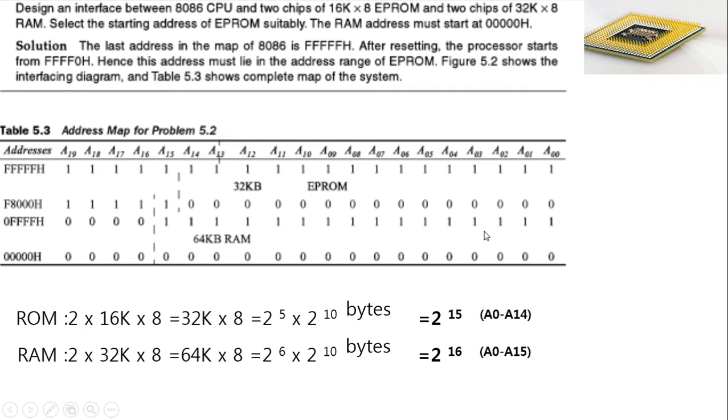Next is the RAM address space. A total of 16 bits of address information are required for addressing each byte uniquely. So the first 16 bits, A0 to A15, are taken for representing the address of each byte present in our 64 KB RAM, ranging from 16 0s to 16 1s. Each of these address values is used for addressing each of the bytes of the 64 KB RAM.